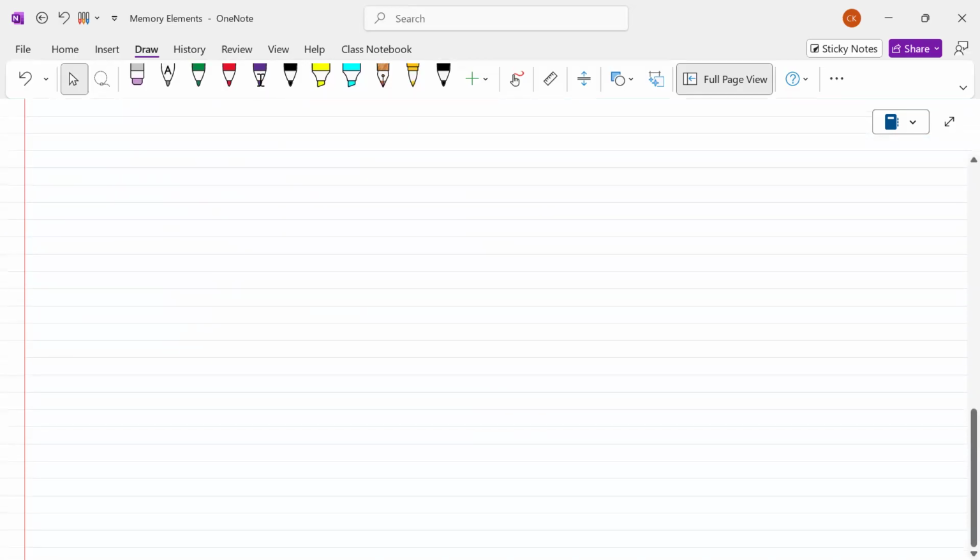Now, today let us take one simple example. What is the problem in the D latch we found? Storing time is less. That means only half of the cycle we are able to store the data, but not the full cycle. So let us see how to solve this problem.